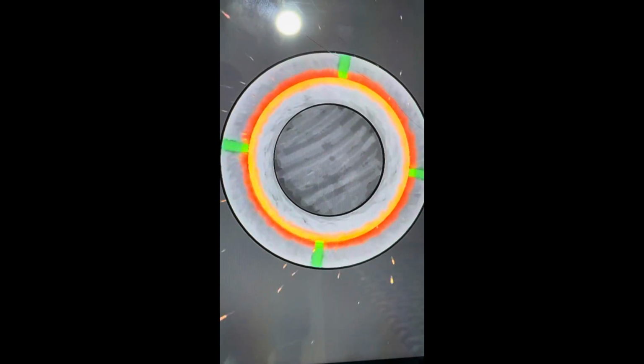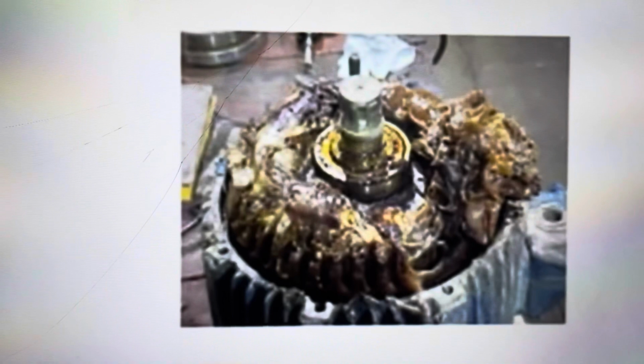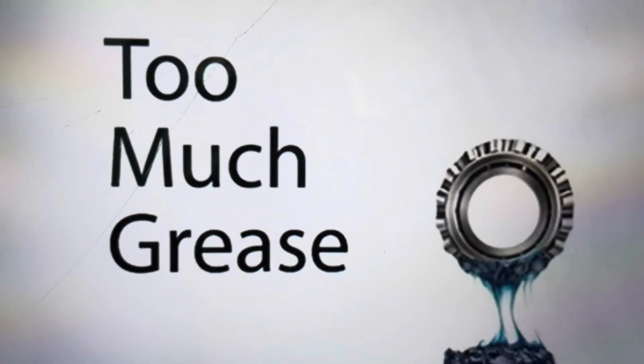The noise, especially for types 1 and 2, occurs when the metal parts rub against each other and the sound occurs. So now, how do we prevent the mechanical noise? The answer is every mechanical part in the motor should have grease, but all of you should remember that excess grease will damage the motor.